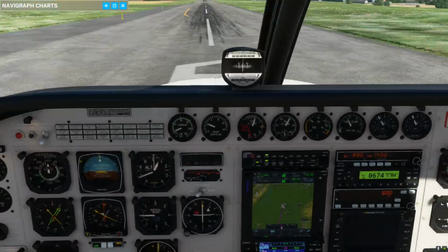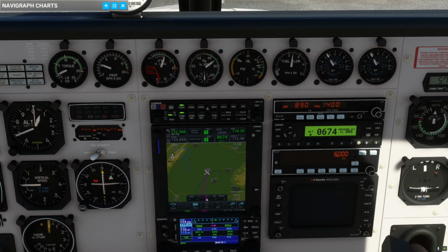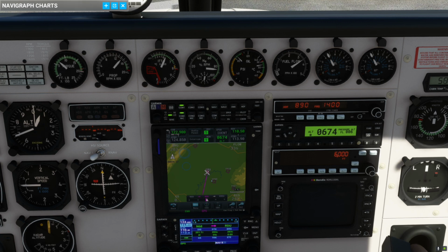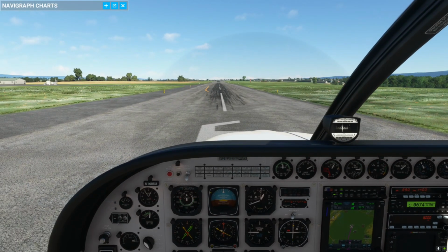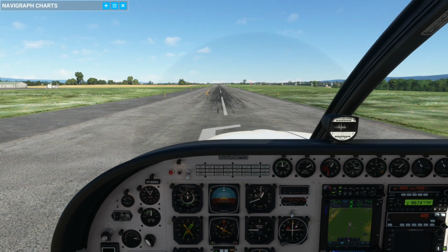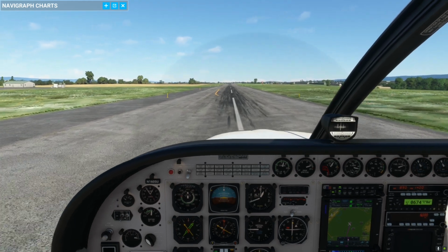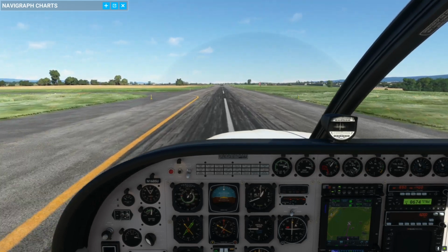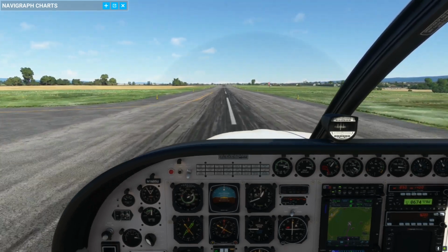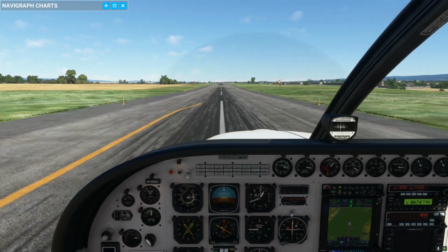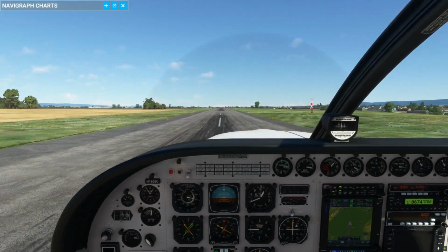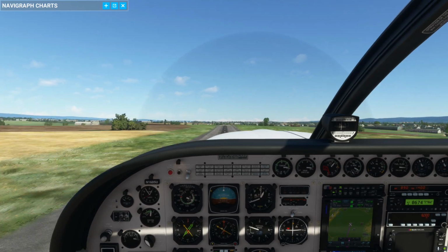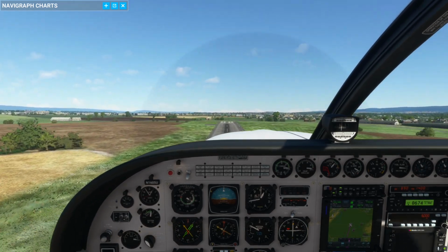All right. 40% load. Oil pressure and oil temperature look good. ITT looks good. We're out of here. Looks like we have a no-wind situation, so just rudder for torque. Watching speed. And rotate. Airborne time logged. Flaps up.